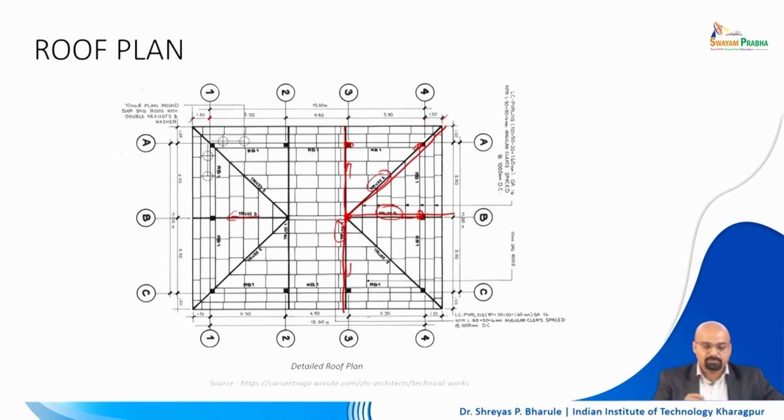Then column center to center location is to be mentioned, but in other case if you are doing a roof plan and it is a wooden roof or a steel roof, then your members center to center is also to be represented, also to be mentioned, because sometimes the trusses are off centered like this one, or sometimes the trusses are in the middle of the column.